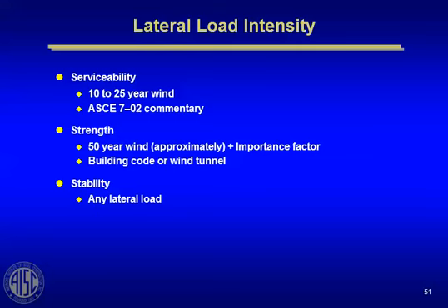Some engineers say, I'm going to check drift for that storm. Well, I found that I think that's pretty conservative, and many of the wind tunnel guys that do perception to motion checks for acceleration in tall buildings, they usually use a 10-year storm as a more realistic storm, or a 5-year storm. And so what we do in our practice, we use a 10-year storm to check drift. And we say, okay, under a 10-year storm, we're not going to let the story drift be more than L over 400. The story height divided by 400.